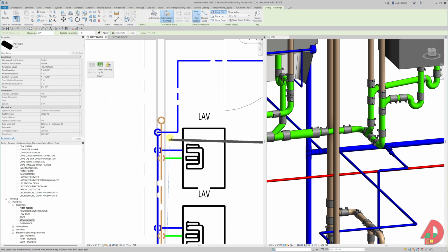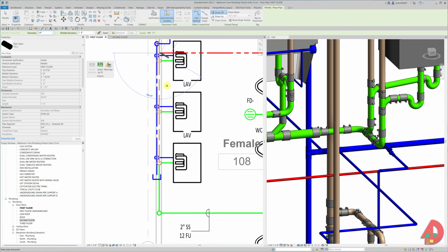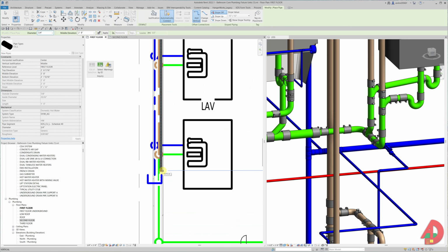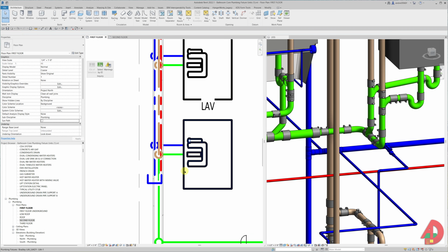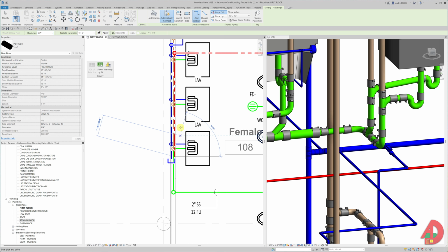And then towards the wall. Drop the elevation to 2'8" around the line in the wall. In order to rise to the second floor, I select Pipe command, click at the end of the line, set elevation to, let's say, something high like 15, and then hit apply.